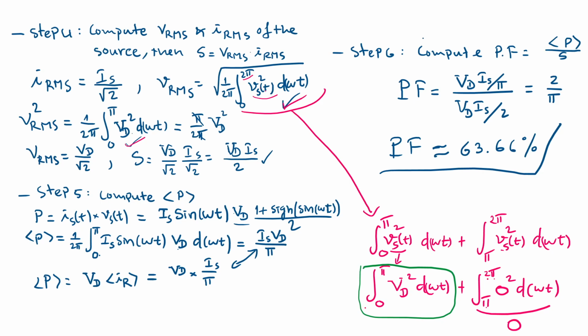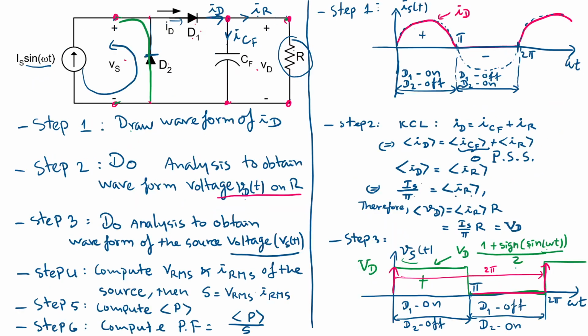Yes. If I want to increase the power factor, I should increase the capacitance, right? No. Please distinguish from a system with inductive load. If you have a system with high inductive load, then you use a capacitor to compensate for it. But this power factor actually happens due to the waveform distortion.